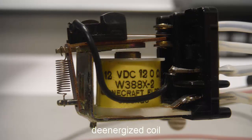One can see the actuation mechanism internal to an ice cube relay. When de-energized, the spring pulls back on the lever and the common in the center is making contact with a normally closed contact at the top and disconnected from the normally open contact at the bottom.